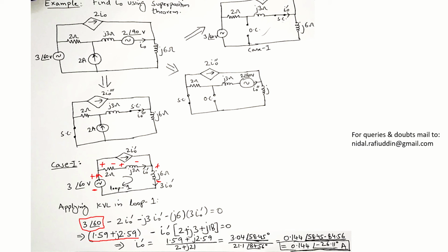If the current is going to flow opposite to the polarities of the voltage source, in that case you're going to get the answer with angles. For example, if you consider the phasor of voltage with angle 60 degrees, that of current is around minus 26 degrees. So you can say that the current is lagging, by less than 90 degrees.